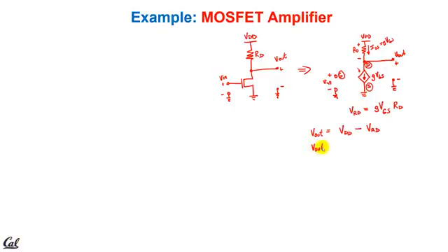So it's going to be VDD minus G VGS times RD. What we see is whatever input we put on, in this particular case, because V in happens to be VGS, is going to get multiplied by the gain and times the resistor and subtracted out from VDD. Let's look at how that looks for a real input. Now, what could a real input be?